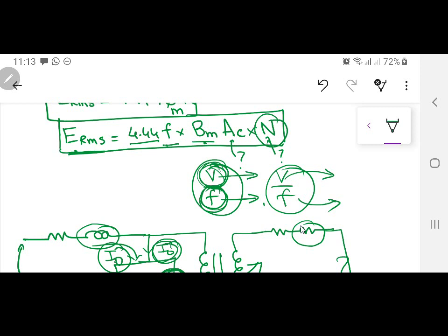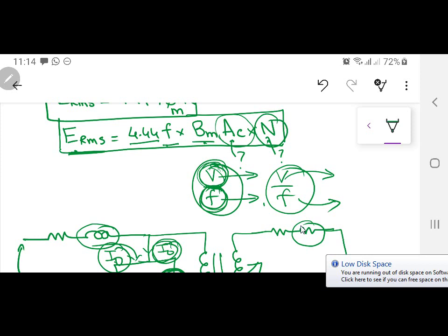देखो एक सेकेंड, area is dependent upon the value of flux in the core, ठीक है। Area of the core same रहेगा, उसको कोई फर्क नहीं पड़ेगा। Yes, प्रॉब्लम क्या पड़ेगी, आपका area of the core उतना ही है, लेकिन आपने क्योंकि wire का size बड़ा करना है, तो this outer dimension will increase, क्योंकि उसके बीच में अब ज्यादा मोटी तार आने हैं। आपको बड़ा करना पड़ेगा फिर उसको, इसीलिए you have to first make it on a paper and then go on towards it.